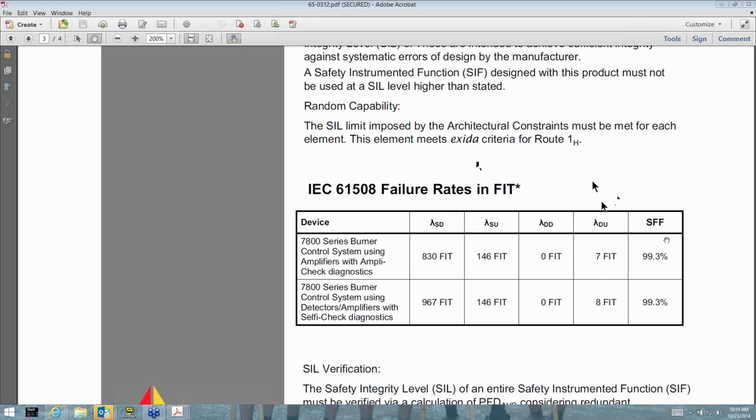The interesting scenario about the safety transmitter, I showed you the various layers of technology that it has. You could just use it as a simple analog output device in a SIL-2 certified or SIL-3 capable application. You still have all of the accountability as far as failure of the device in a saturation. The transmitter saturates to like 3.8 milliamps, and once it does, you know that that's a failure of the unit. You don't know what failed until you walk out and look at it, but you have indication it failed. But if you chose to use the additional layers, it's in there.